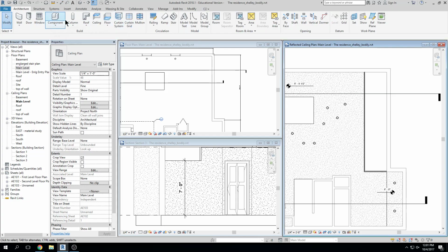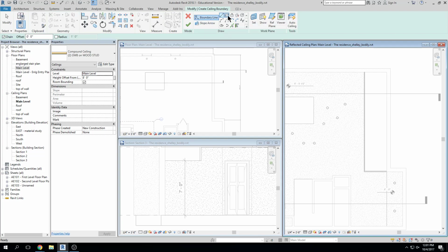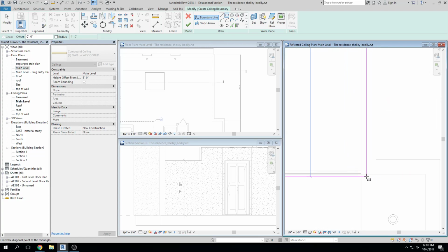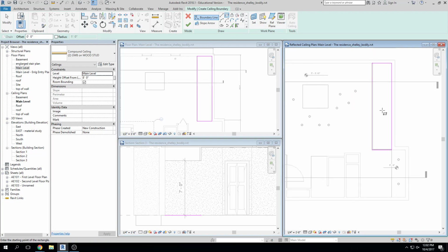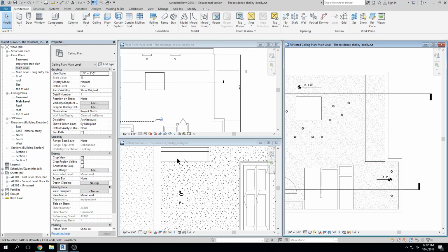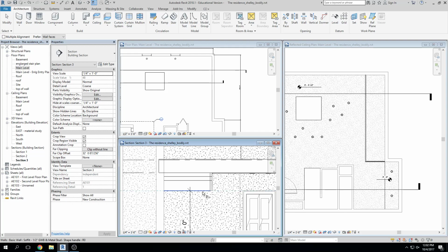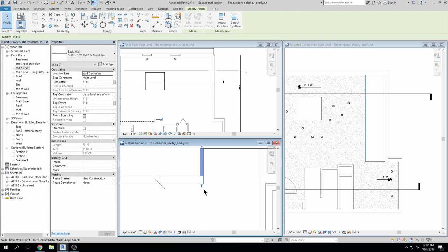Okay, so I go to ceiling, I go to sketch, here it is. The ceiling is going to be, we'll just leave it there and we'll alter it after the fact, right? You forget, oh, it's not 8 feet, it's 7 feet, but we'll alter that. I hit finish. You think, oh, that's not right, right? I can grab it, I can MV move it down, I can AL align it, AL, click, click, which is probably more what you want to see or use, the tool you want to get used to using.